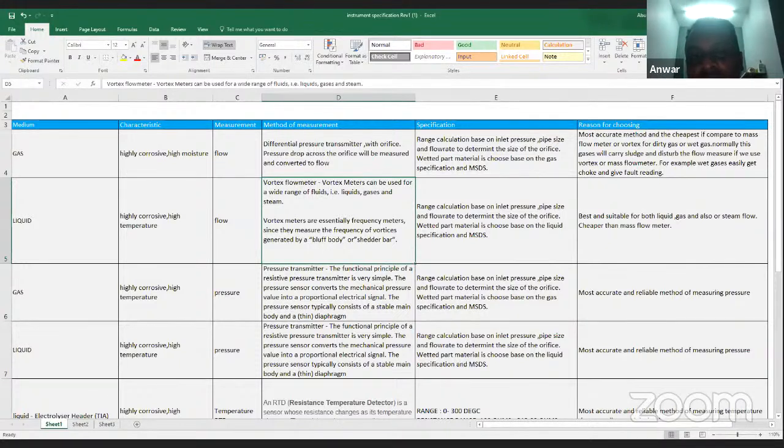We also use other methods in terms of calibration. We have multiple equipment upstream and downstream. If the downstream equipment is already due for calibration, we will see the value and compare it to the upstream instrument value, which is still within its calibration period.